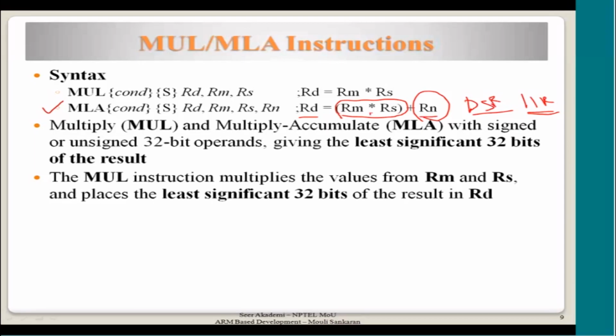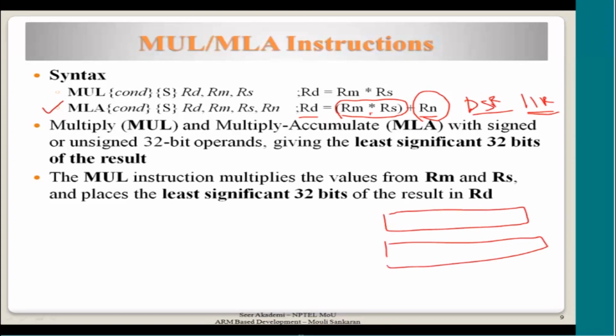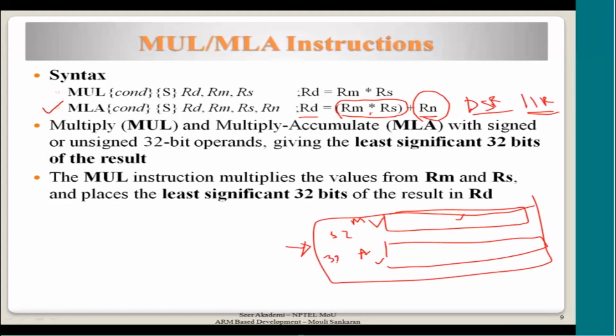So what is the use of providing one instruction doing both? Because you are saving a lot of execution time. If you have MUL and ADD as separate instructions, you would spend one cycle executing this instruction, and then ADD will take one more cycle to execute, plus pipeline access, all that unnecessary power wastage, as well as code size, since one instruction occupies 32 bits, whereas this will take 50%, 100% more for every MLA.